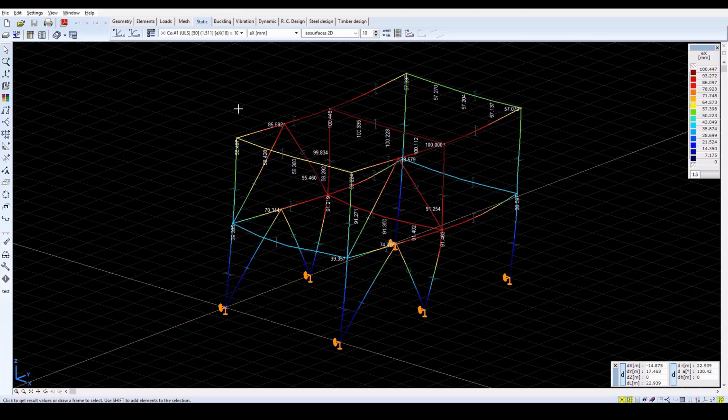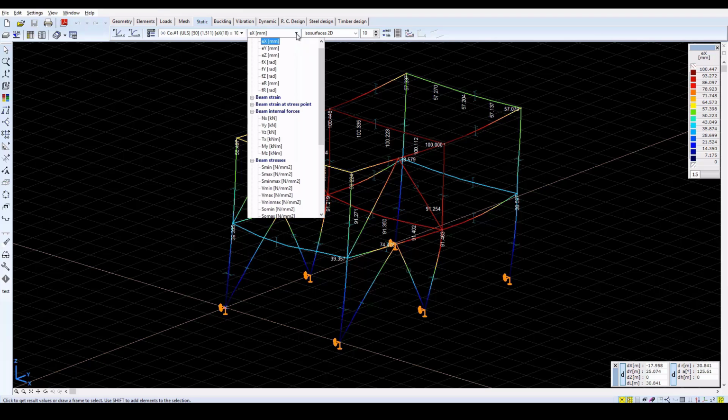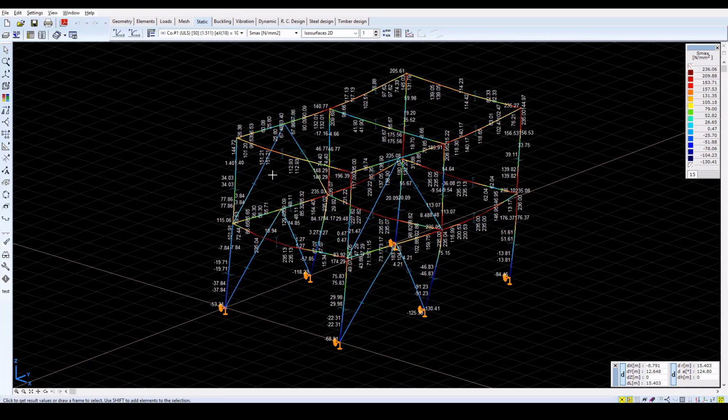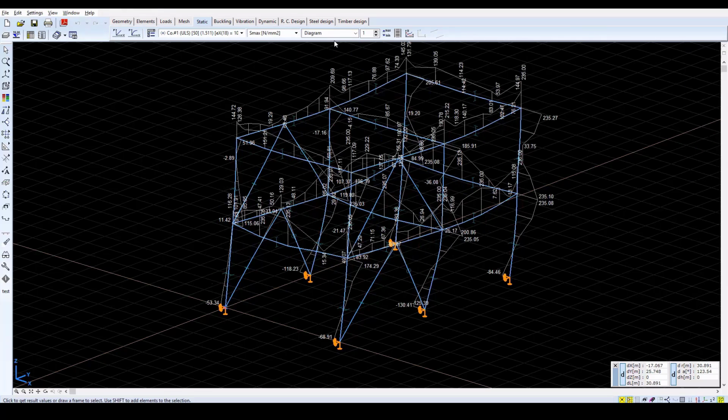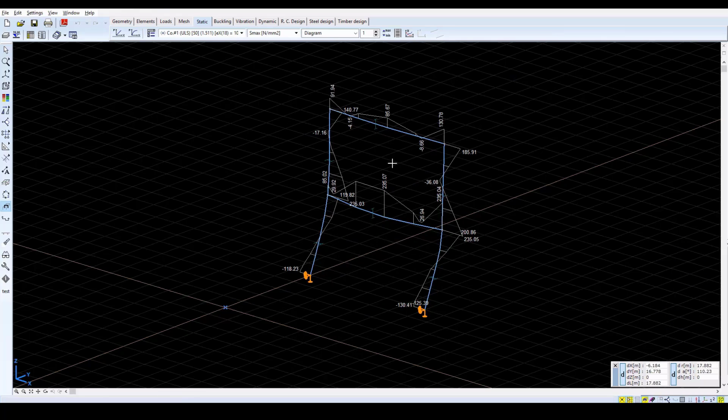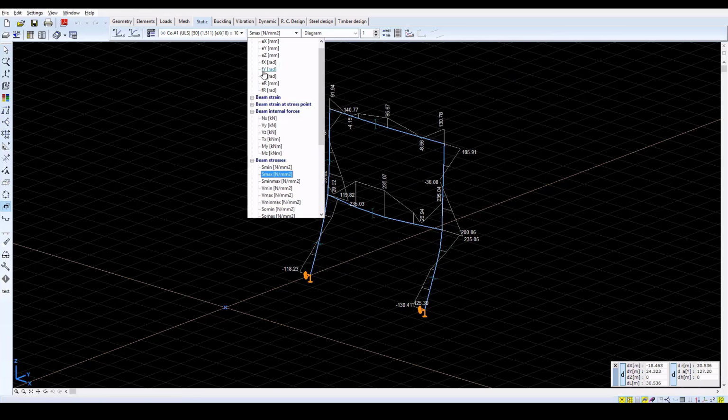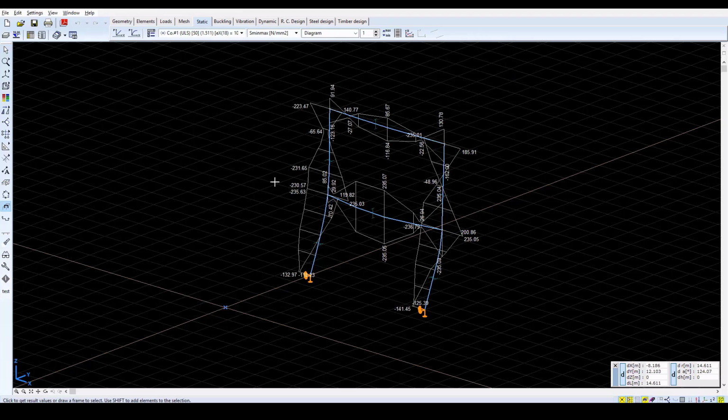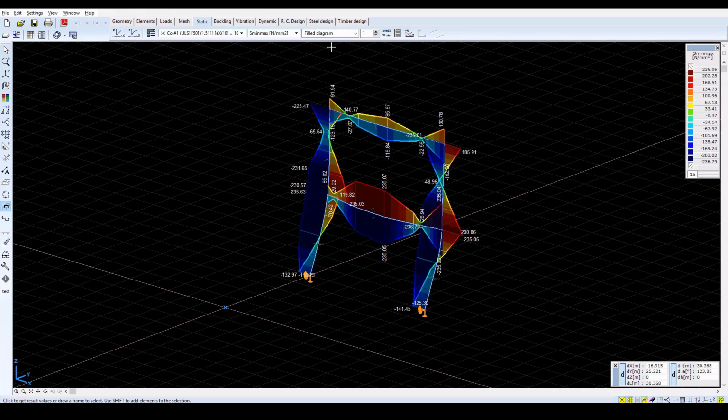With the analysis completed, the displacements are shown on the deformed shape for the last increment, the 50th. Let's examine the progression of the plastic hinges in the intermediate frame. For better visualization of the intermediate frame's results, the corresponding part is activated. Select the stress minimums and maximums results display, S-min-max, in the filled diagram mode.